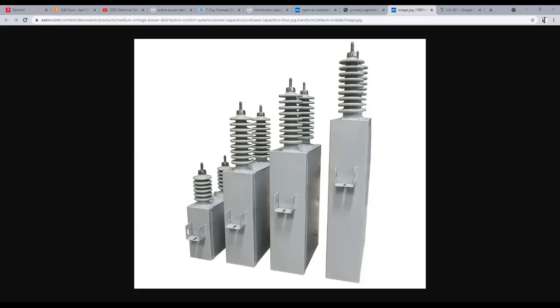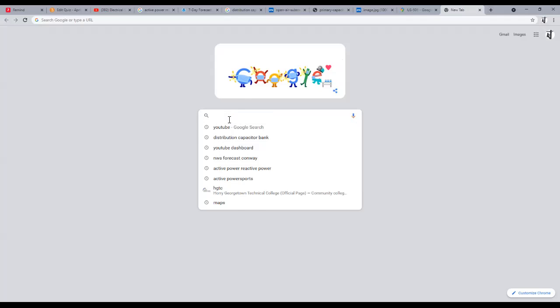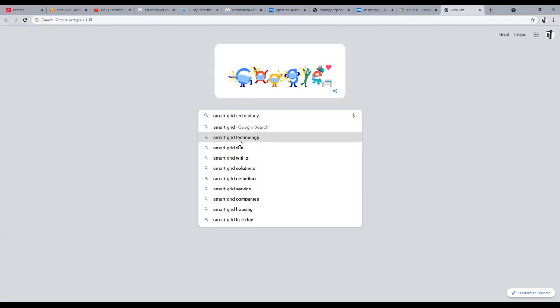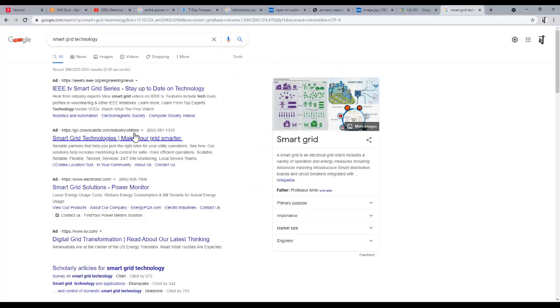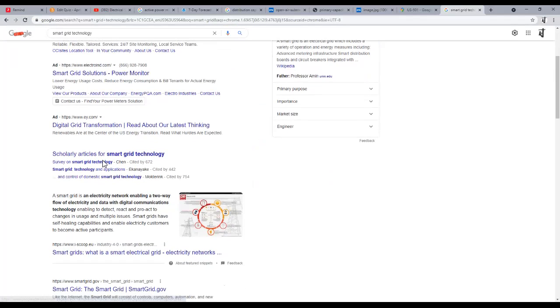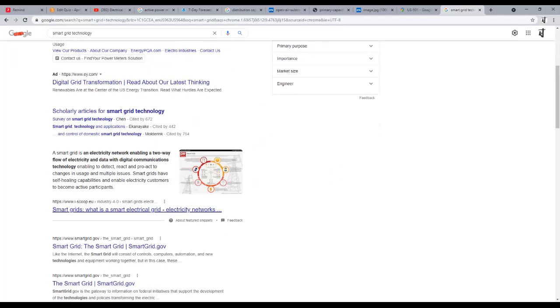Good question. I worked on this project a little bit before I retired. We went out and installed medium voltage sensors at specific places on feeders where they could monitor the voltages, whether high or low, or if they needed to kick on a cap bank or raise or lower a regulator. Yeah, we had some of that. It seems like most of this we could check from a computer, like it's all documented in one place.